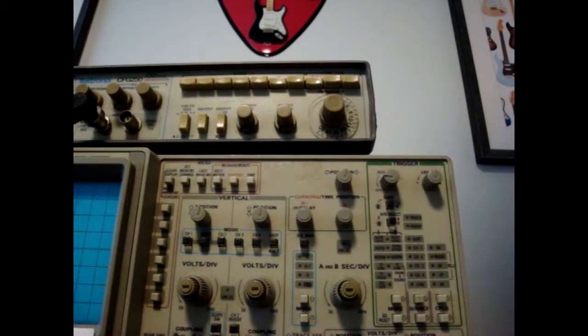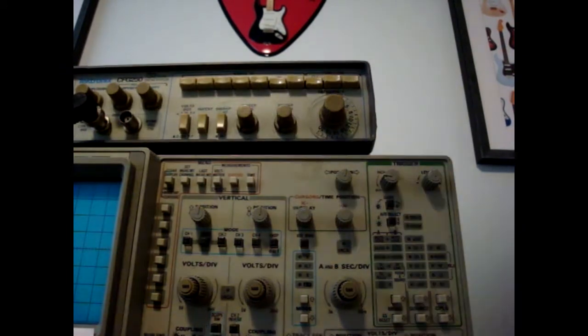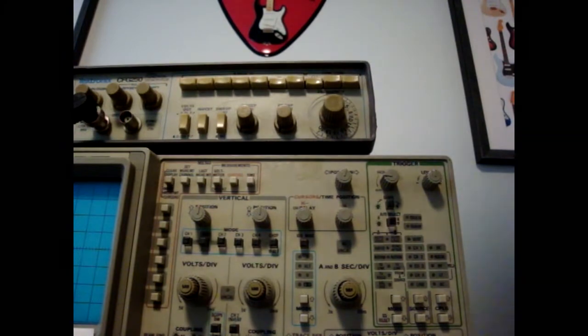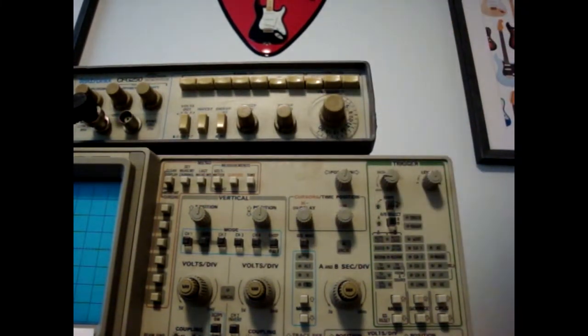An easy way to check is I take my signal generator and run it into a little bench amplifier I have here, an old PV solid state amp, and I run it into the speaker, and I go from the low frequencies up to the high. I'll sweep with the frequency knob, and at any point if I hear any kind of strange distortion or rubbing noises, I'll know that speaker's bad.